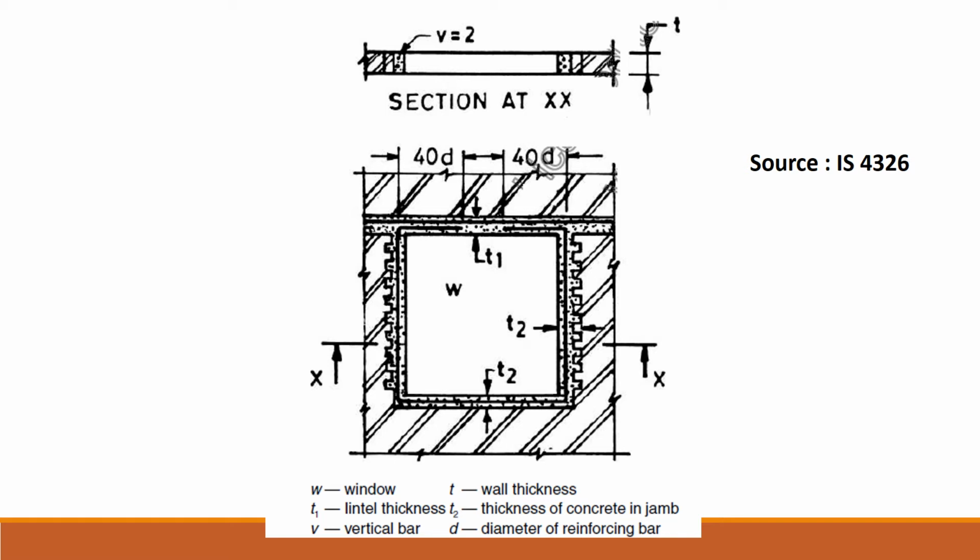Now the concrete is cast into the brick by toothed elements, and the reinforcement is taken throughout the jamb and sill level of the opening, whereas it ends at a distance of 40D from the ends or corners of the opening at the lintel level in the lintel band.